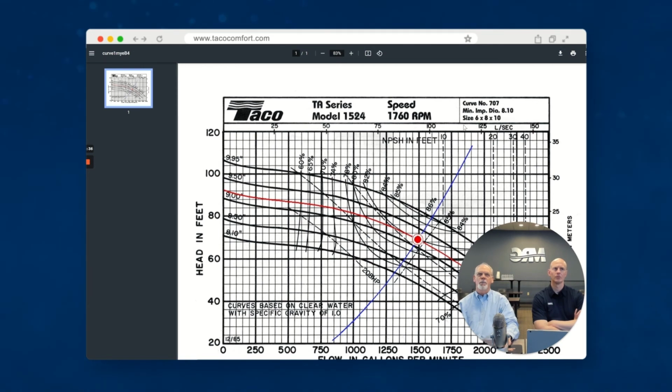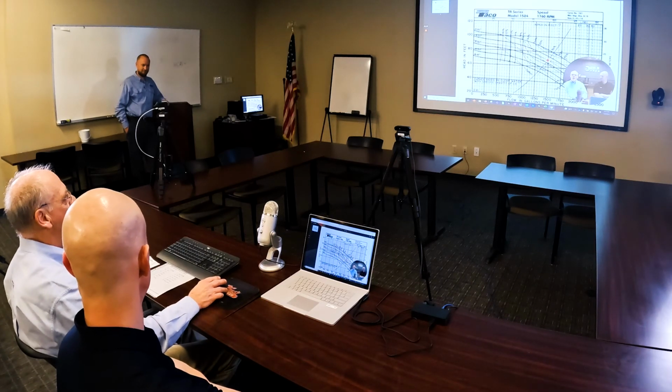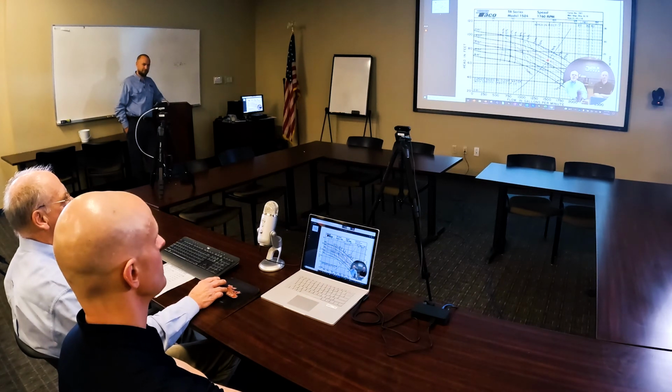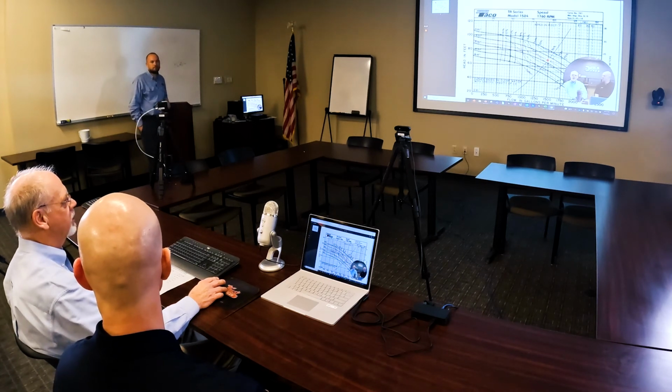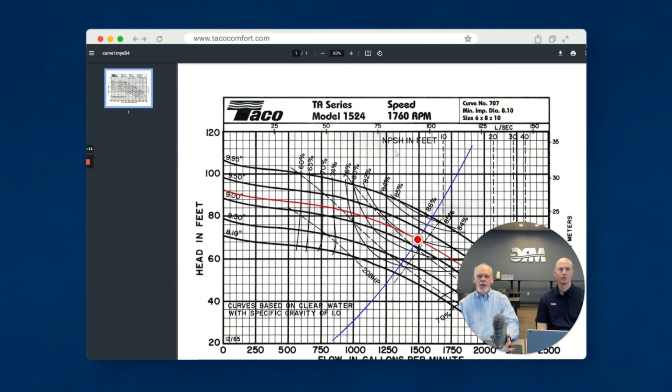All right, so this would be another pump that would be a good selection depending on what you want to do. This pump here is a 6 by 8 inch pump, so you've got an 8-inch suction, you've got a 6-inch discharge. With 1500 GPM, you're probably going to have an 8-inch pipe coming down to it. One good thing is to always have larger pipe than the connection of your pump. That way you've always got a supply of water available to come into that pump. Like I say, the pump is pushing, it's not pulling. So you have to have a good supply of water coming into it in order to push it out. And that's where you get your net positive suction, is when it's trying to push out more water than it can take in. And you've got a cheat sheet that tells you what the flow would be for the pipe diameter.